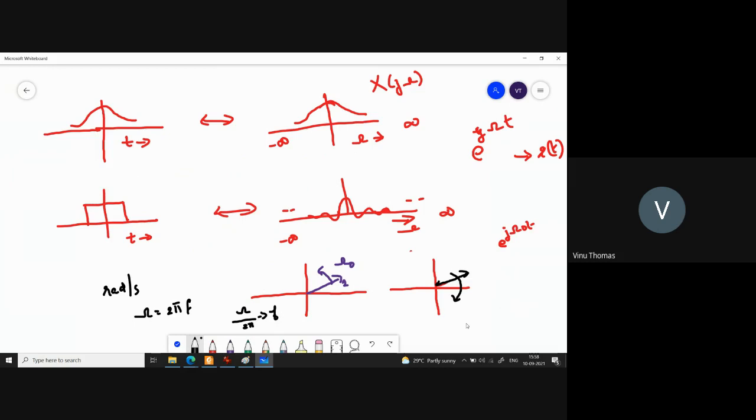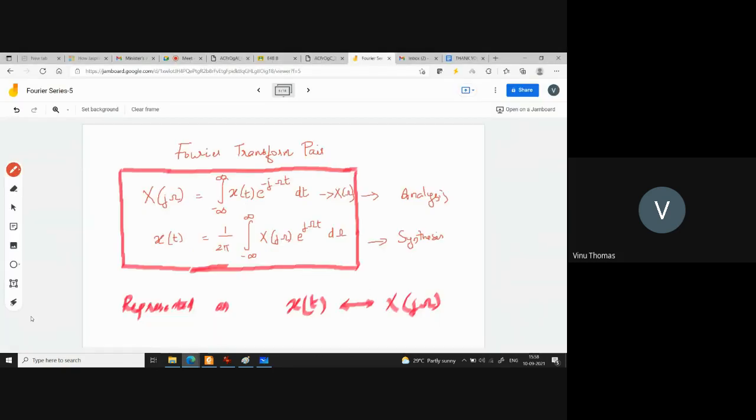Which means in theory, at least for the complex exponential, you can think of a signal of frequency, let's say minus 1 kilohertz. That is possible. You cannot picturize a signal of frequency minus 1 kilohertz from your function generator. From the function generator, you have positive valued frequencies. Whereas at least on paper, for these kind of phasors, you can picturize signals that are phasors rotating in the negative direction and therefore having negative frequencies. Okay, so that's about your Fourier transform pair.